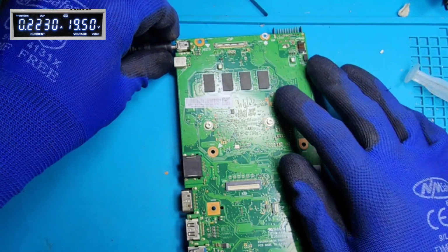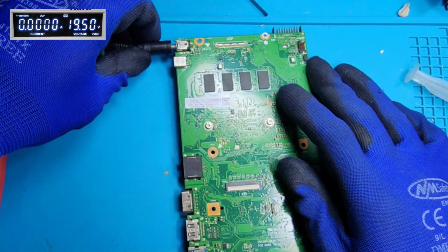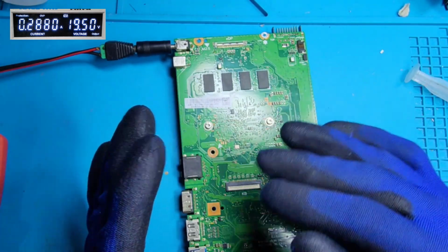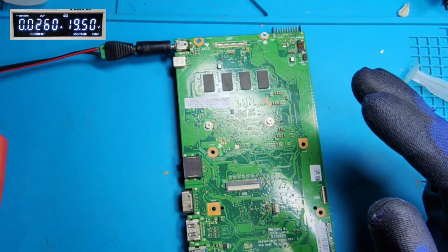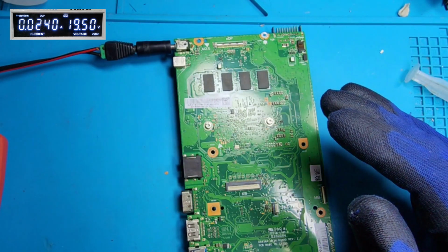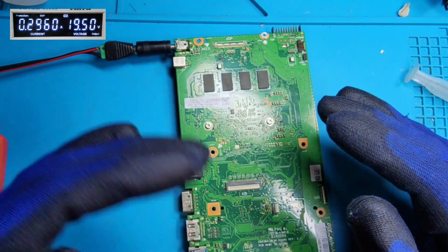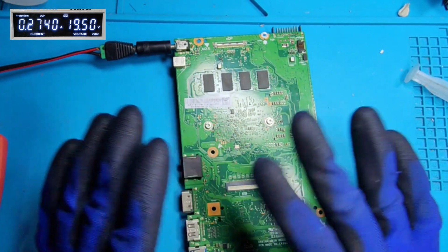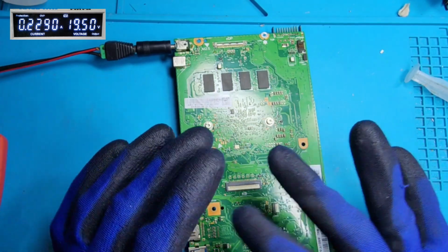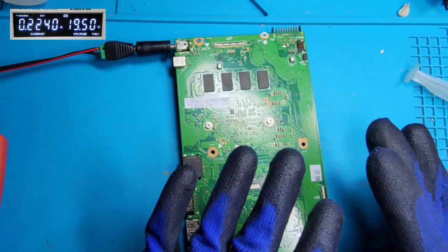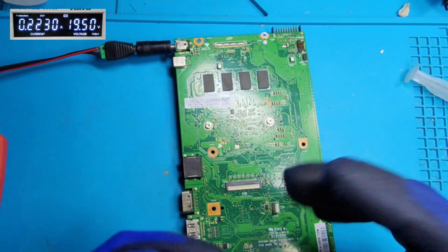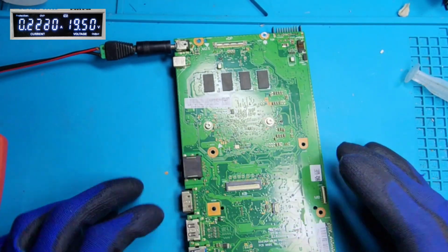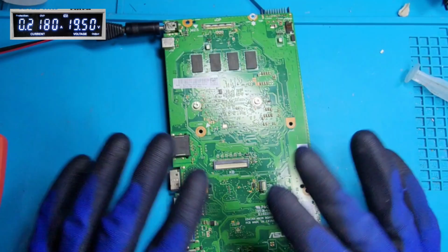So this time when I connect the adapter, it is not going to zero, it is going to standby, so that is okay. So there is some ampere reading. Did you see that? 20 milliamps, 24 milliamps, then back to 200 milliamps. So that is fine. But before, it went to 0 milliamps then back to 200 milliamps. So that is actually the main power relay switching on and off. So that is the scenario there. But this time it is okay and working fine.